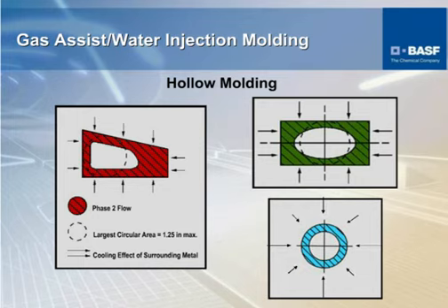But in a lot of cases, that may not be your cross-section. So you look at a trapezoidal type cross-section, and you can see it's not going to core this out uniformly, but you'll still get a good hollow cross-section, but you might have some other issues. You can see here this very thick section is still going to be thick. You've cored it out a lot, but it's still thick in this area here. And the same with the rectangular cross-section. You do get a good core out, but you can see close to the corners are still fairly thick.